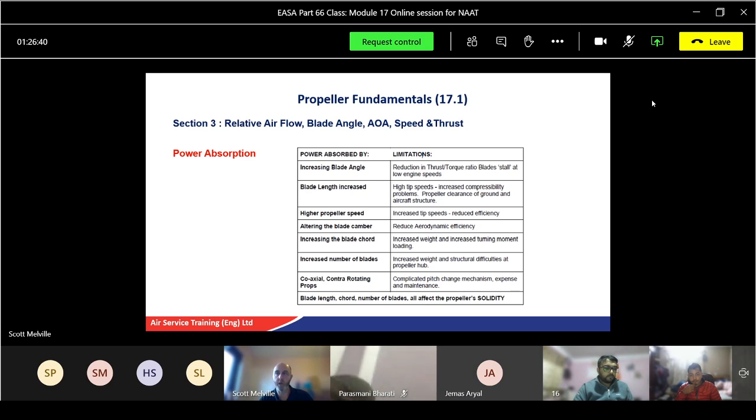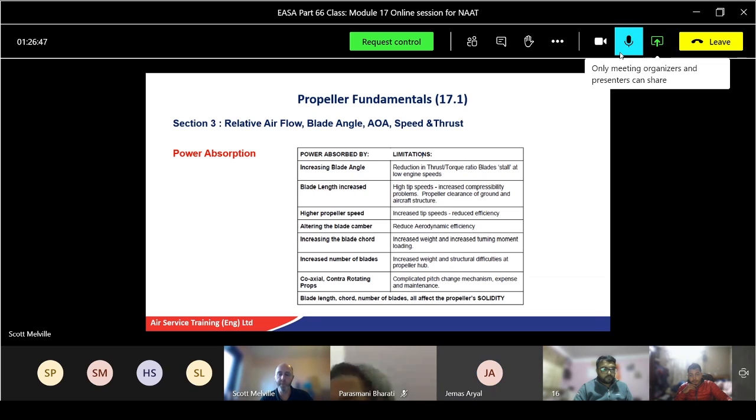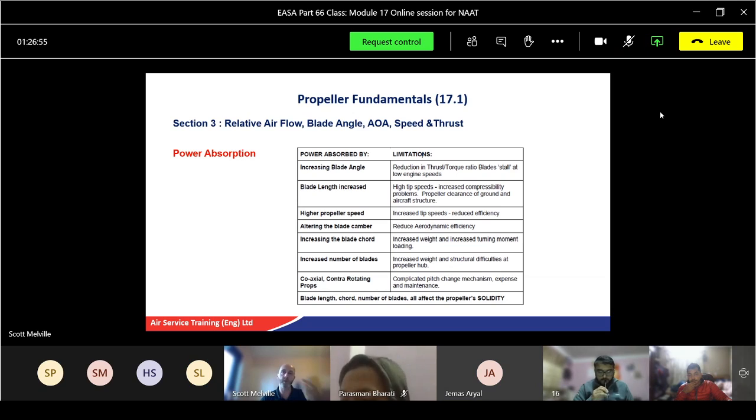What was the purpose of the cuffs put onto the blade root on a propeller assembly? Improve the airflow around the blade roots. Yeah, because you've got the hub assembly going relatively slower than the tip, which is going quite fast. Depending on the design of the blade, that determines how much vortices or turbulence comes from the tip. But likewise at the blade root, these aerodynamic cuffs prevent turbulent air which could go down the intake of the engine and cause problems with the engine. So yeah, good.